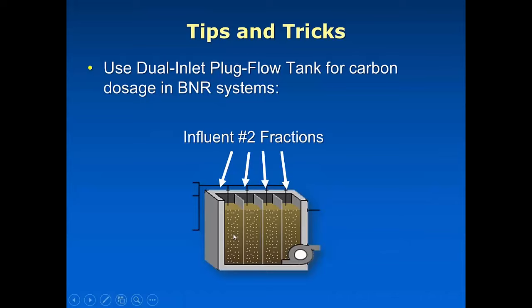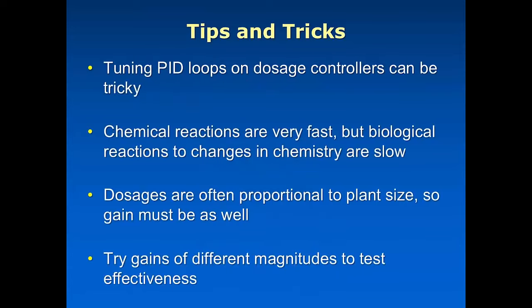And that's the way I had it set up during that MLE portion, because of course the first tank is the anoxic zone. So that's just an example of a very useful setup, and you'll notice that many of our objects have 2 connection points like this on the front end. One of them is designed for the flow that's coming from the previous upstream object, and the other one is designed to very conveniently add something like COD dosage.